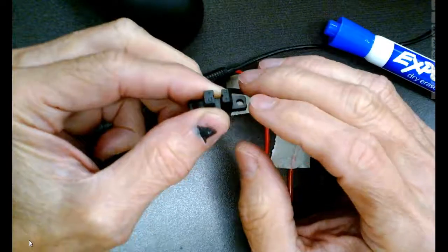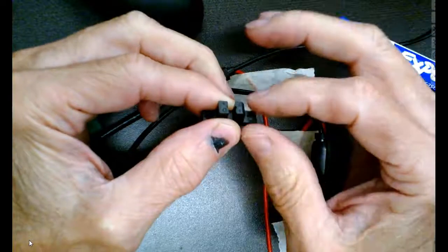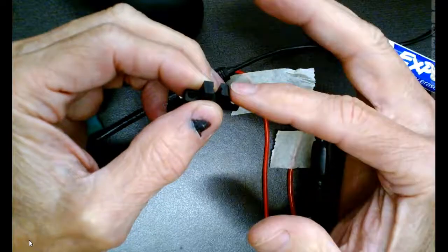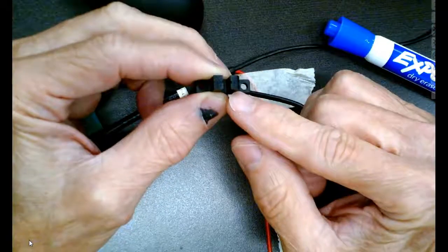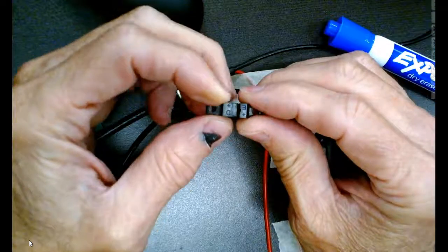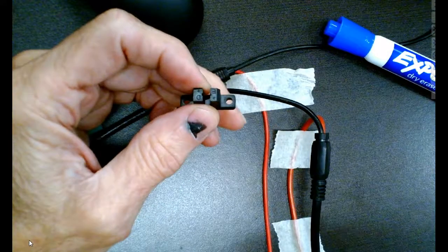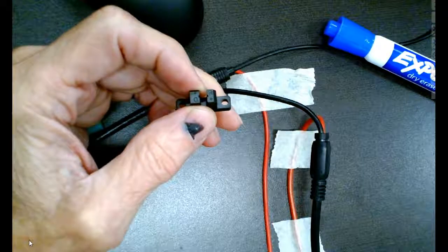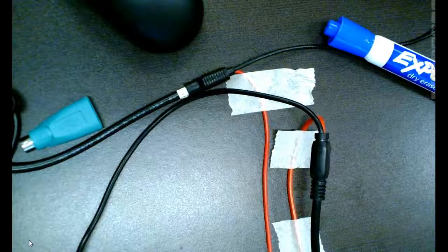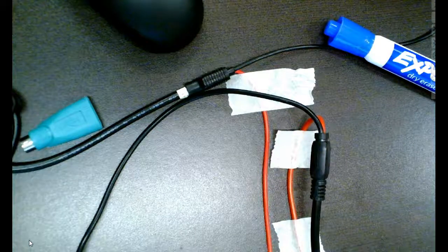And it's got a photodiode in there, so you'd have to do some little math to decide what size resistor you're going to use. So if you use like a 5-volt supply, or you can use just about any DC supply, it's just that you always have to put a dropping resistor in with your emitter. You put a dropping resistor across your detector, so you can see the output. Do y'all understand what I'm saying? So this is an optical interrupter, which is nothing but a through-beam, but it's got its own name.